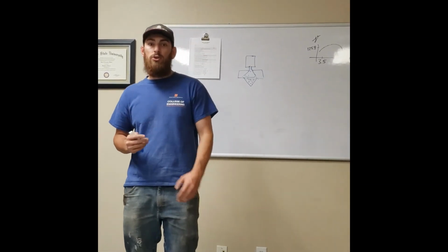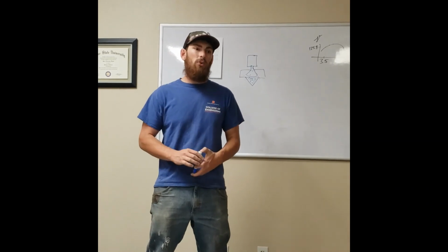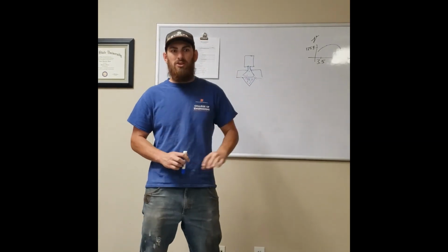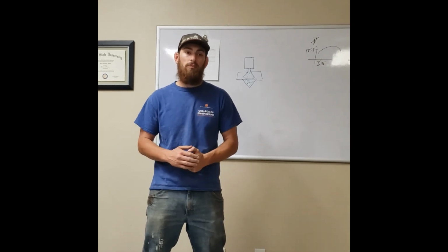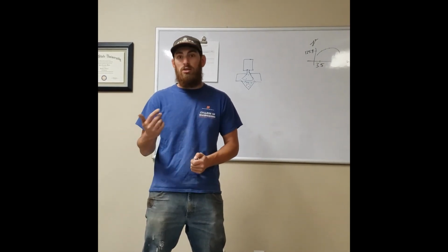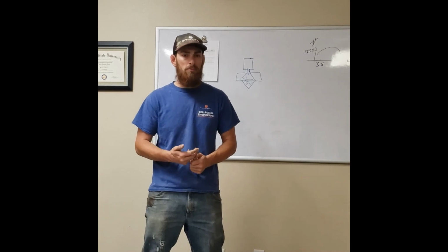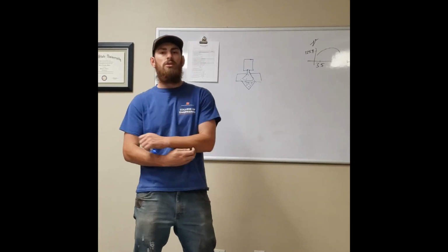The nice thing is the Nuke gauge basically does all that for you without doing any of this extra stuff. The Nuke gauge is what you'll see on almost every job site where you've got to do some sort of compaction testing. It'll give me my moisture content and my density, wet and dry. And it basically just eliminates the whole need for the sand cone.